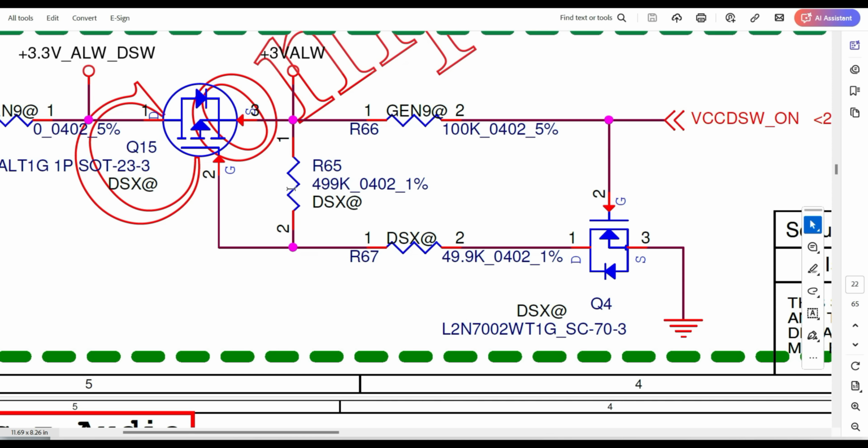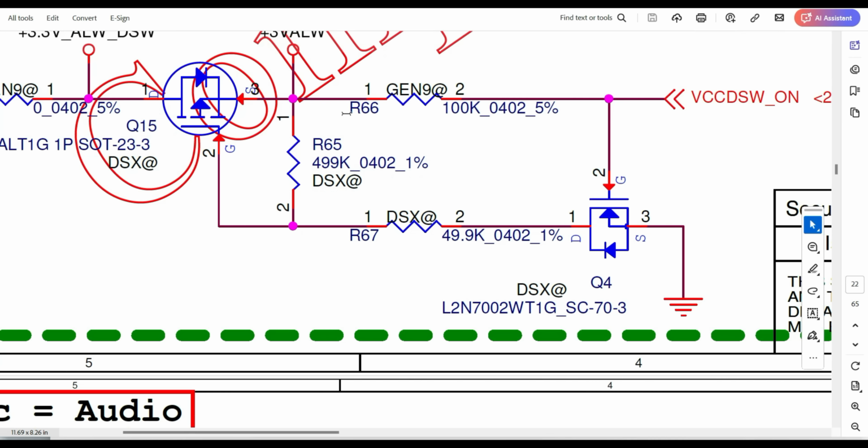Now this we consider as R1 and here is R2. Okay, the characteristics of this component, here is the MOSFET, N-channel MOSFET. In case this N-channel MOSFET gate gets the voltage, then it will connect 1 to 3, meaning here it will be series, and this voltage destination will connect to the ground.